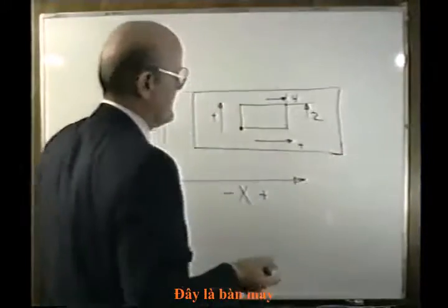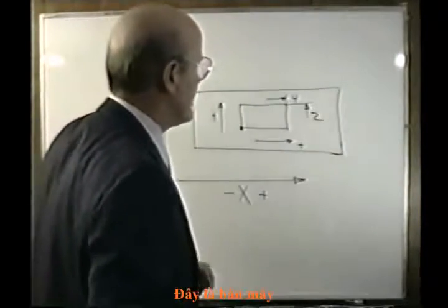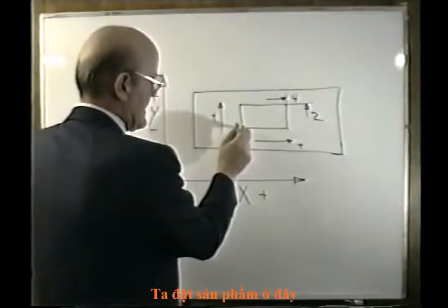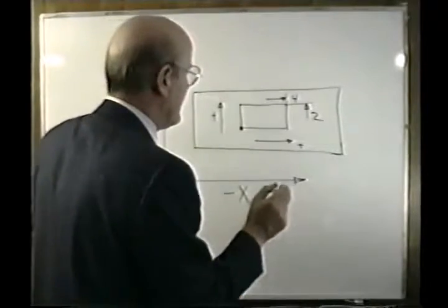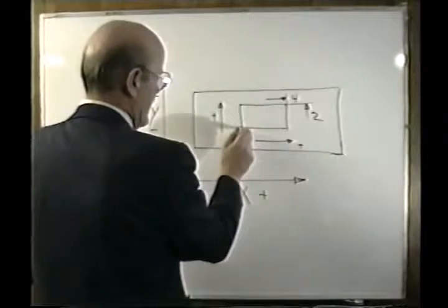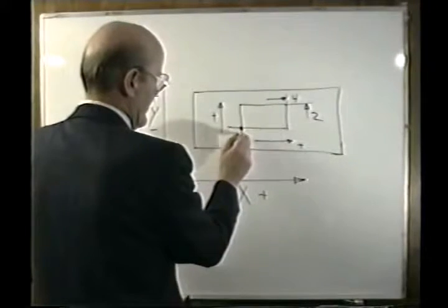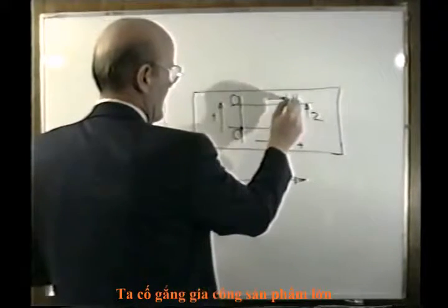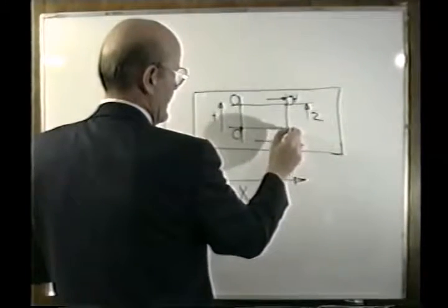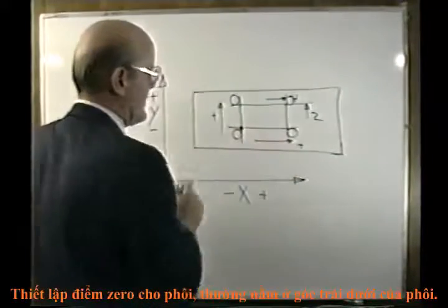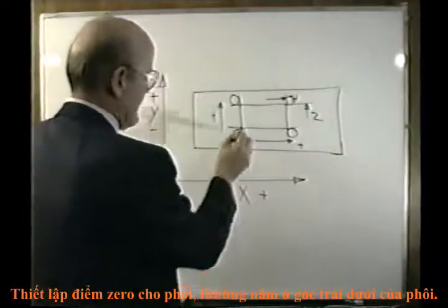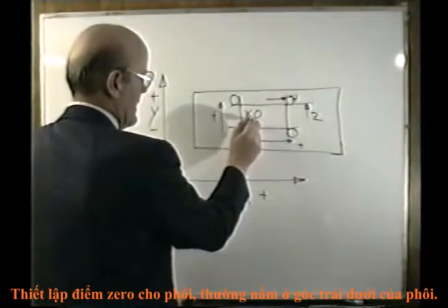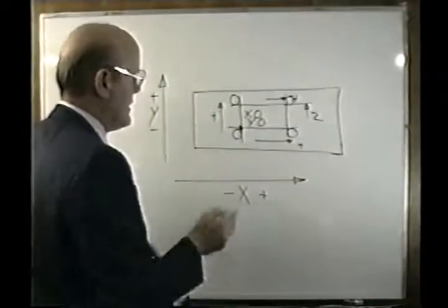Now, through coordinate system setting, which we'll do later, we will tell the machine that we want to start counting from here. Now, to define where these different points would be located, if we have a cutter that went around from here to here to here, down to here, finally across to here, if this is 0, that would be called x0 and y0.